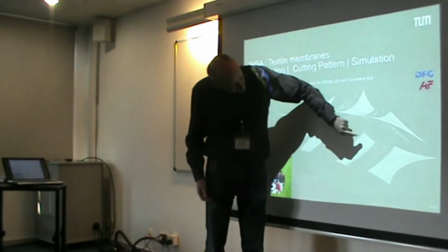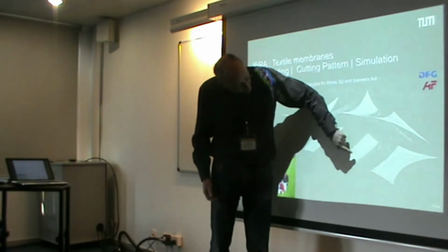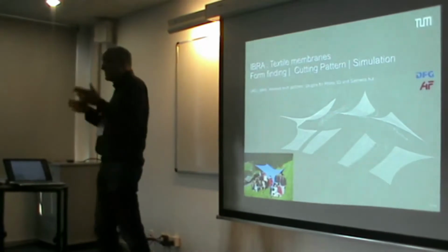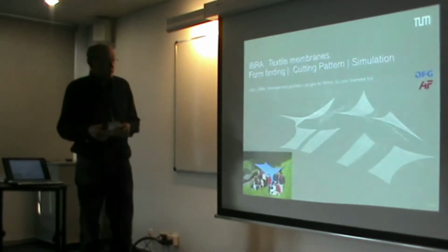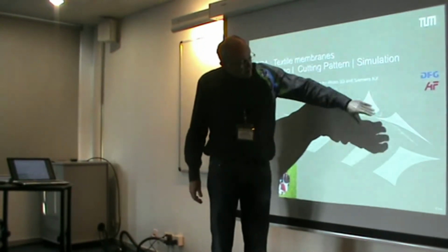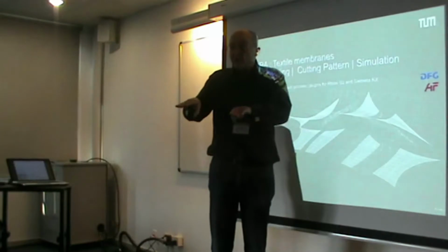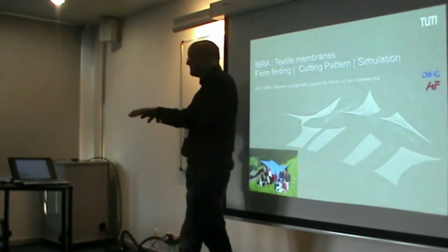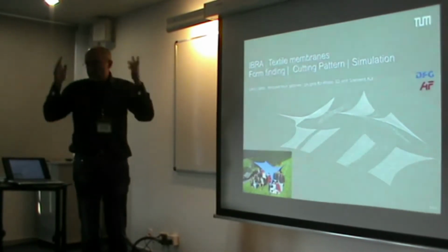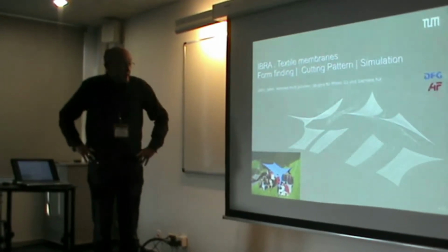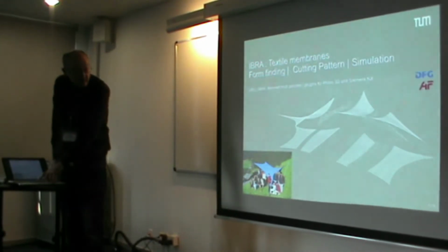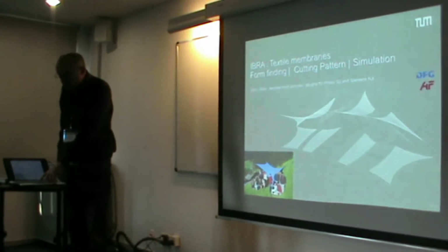And if you look closely, you see here that we have different parameterizations which don't fit. That's more or less the numerical or the mathematical part of the trimming exercise, where obviously the surface was just composed of non-adjacent surface patches, which is the reality. People just put things together, don't care at all how they're parameterized. And so we have to deal with both of these kinds of trimming problems, which basically, of course, are the same.